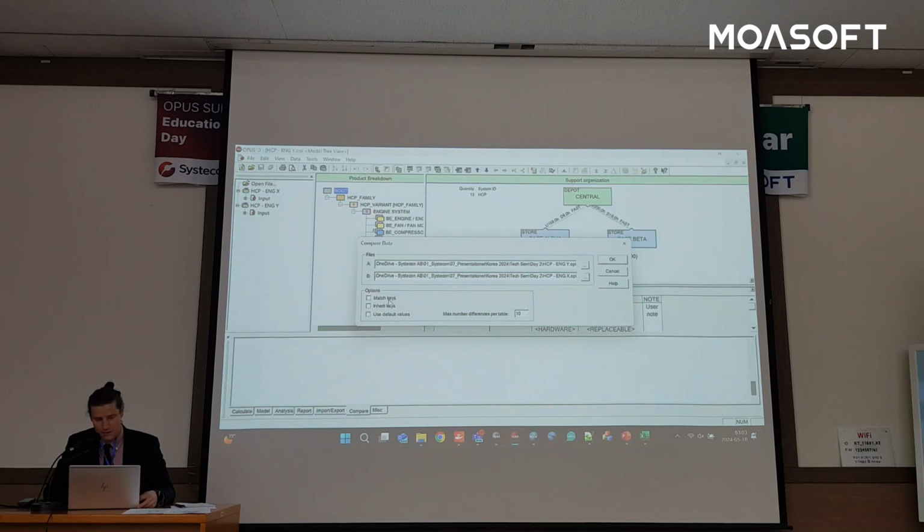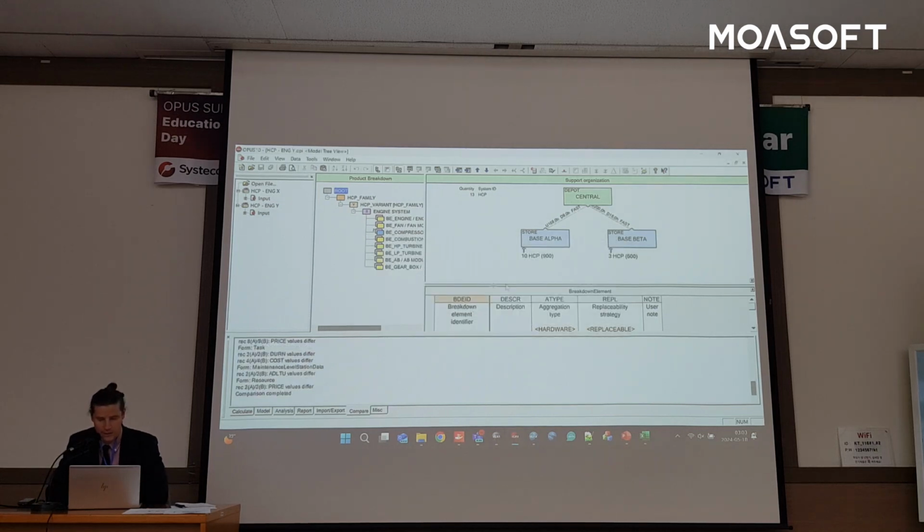And then I want to match the keys, so the identifiers, from all the identifier columns. Even though they are on different separate rows, I can still match them. And that's all I need to do, and just click OK here. Then I get a list down here in this beautiful log window at the bottom, where yesterday we were looking at some warnings and errors. But here you see there are different tabs. So here we're looking at the compare tab, where we end up, and we get a list of all the differences between those two files, sorted per table.